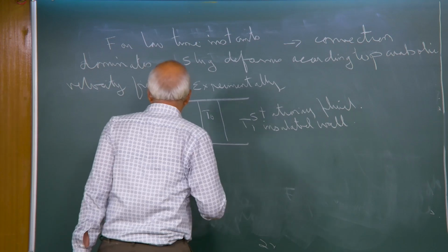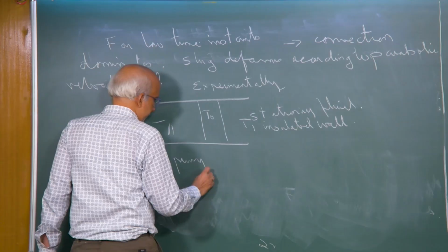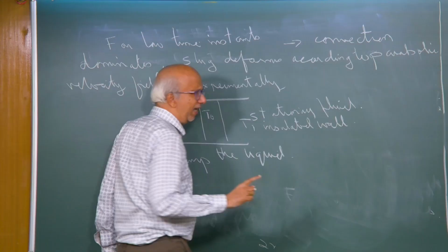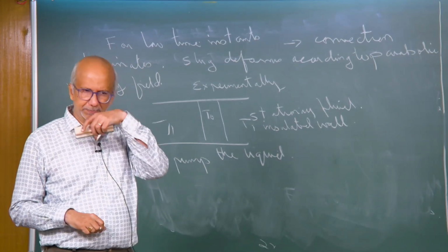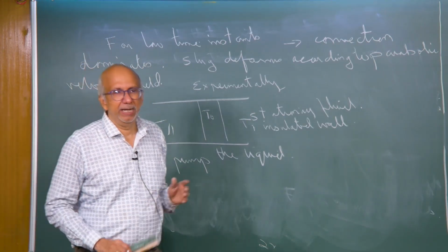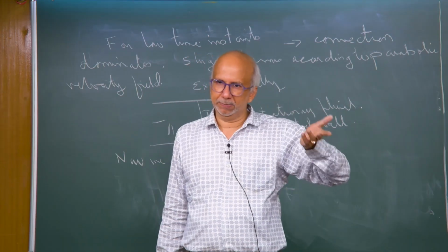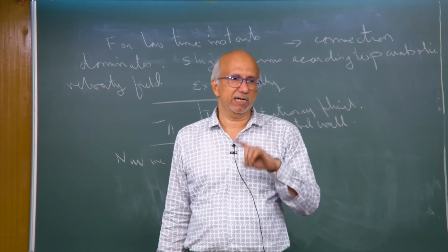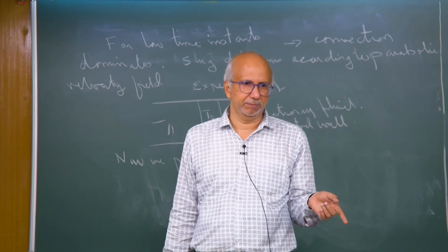Now, we pump the liquid and again I get a parabolic velocity field. Okay. But the point is, in this problem the liquid is stationary, and the temperature is also uniform and steady. So, when I start the pump both the velocity and the temperature will change with time.